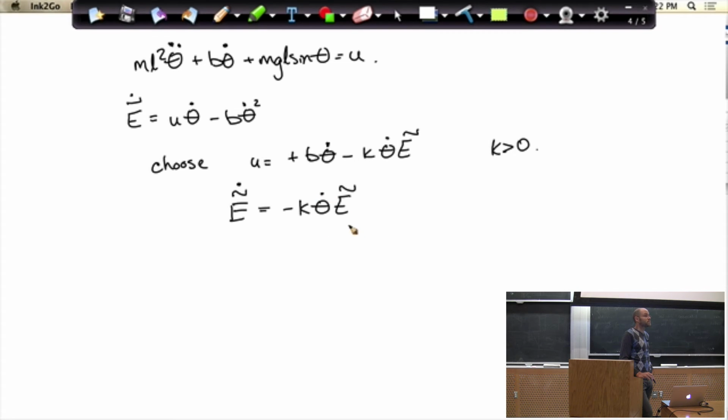So with respect to underactuation, one potential advantage of putting theta in the controller might seem to be that you've got a torque speed curve for your motor. So you might be able to put out more torque at higher speeds anyway. Yep, in terms of physical that's true. Behind that, I'm wondering if that's a part of choosing that controller. Sure, it might be. In practice, this works well, so it's going to work well for more complicated systems too. Right, and there are little things like that that might actually make a practical difference in why it works well. Yeah, I believe that.